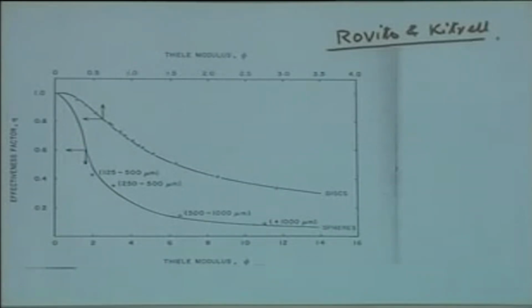If it is first order you multiply, let us say, eta into K2E0 upon Km, the pseudo first order rate constant for an enzyme catalyzed reaction, or if it is zero order, K2E0, and you multiply by the effectiveness factor, if you are aware of that.